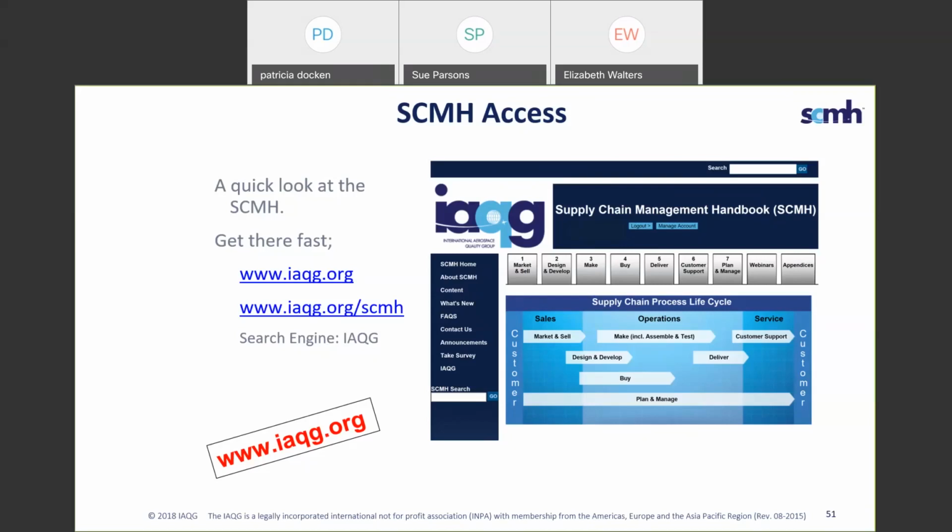Okay. Oh, and hey, Sue, I want to go back to that previous question about control plans and receiving inspection. I mentioned, sure, you can do them. As I think through that question again, I'm not sure how effective they would really be. Yes, it might tell you your variation on product that's coming in, but it almost seems very after the fact and reactive, as opposed to a control plan that's being used in the manufacturing process to monitor and manage those characteristics right there in the process that you're trying to watch the variation on and prevent defects from being created, or at least passed on.